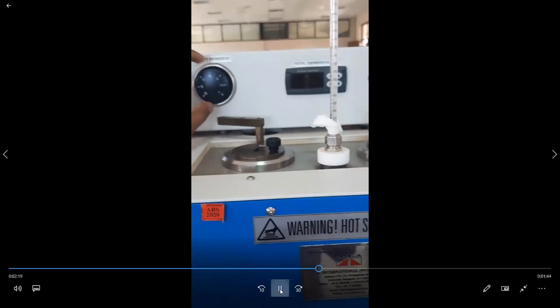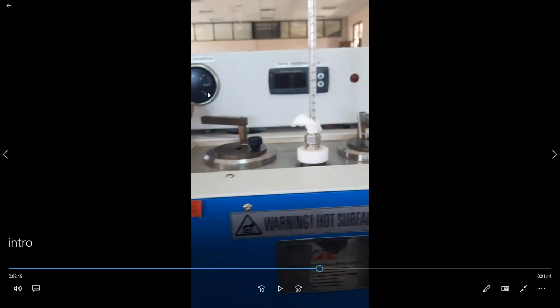How to operate this apparatus? This is the heat control. You can see 10 degrees Celsius, 20, 30, 40, 50, up to 100. Up to 120 we can heat this water, and then we can keep the sample also up to 120 degrees Celsius. Here we need to take time. By measuring the time to collect 50 milliliters, we can derive the viscosity. We have an equation for this apparatus, so using that equation, if you know the time to collect 50 milliliters through that orifice, we can measure the viscosity at that temperature.